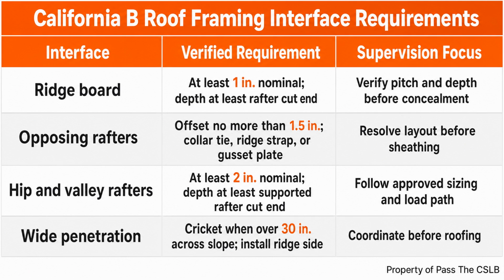The sequence begins with a 19-inch strip laid parallel to the eave. Then, 36-inch sheets are applied, so each course overlaps the previous course by 19 inches. The geometry creates 2 layers over the deck rather than relying on a normal narrow lap. The practical effect is slower drainage on the shallower roof. Water has more opportunity to linger and move under laps, especially with wind-driven rain. The double application creates a more protective underlayment condition beneath the shingles.